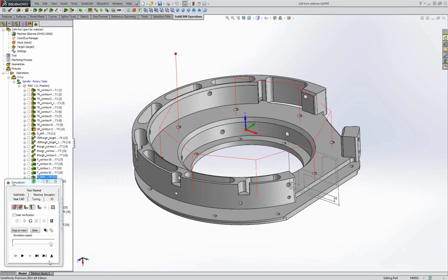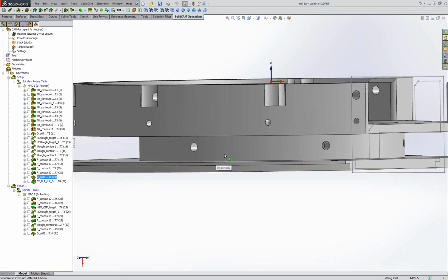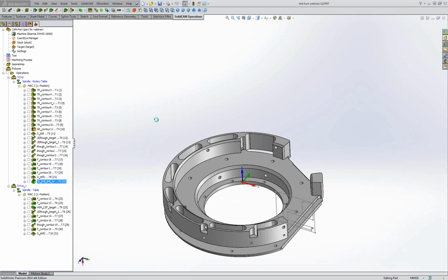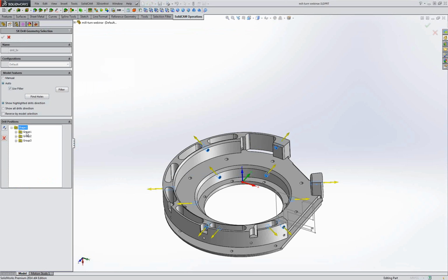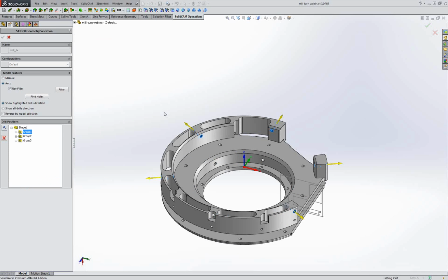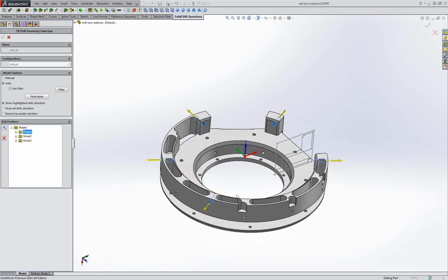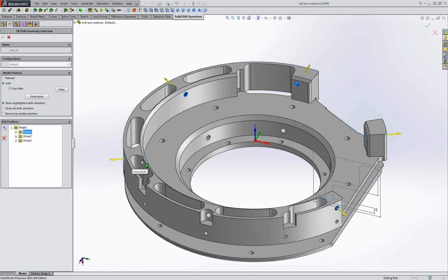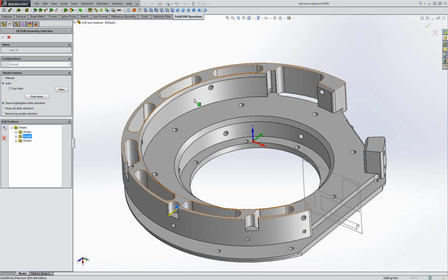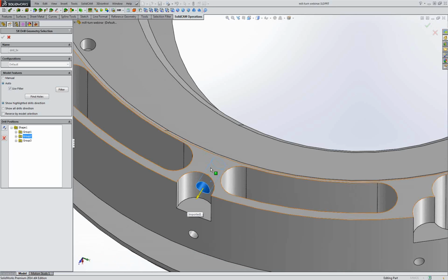And for drills on side, on this diameter, and also for internal diameter, I will use only one operation, multi-axis drill. Here we have the definition, edit. We have three groups of drills. Group 1, they are the same diameter, but maybe differences on levels. So one group is this, and the second we have here the drill with the same diameter but not the same depth.